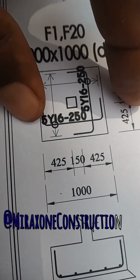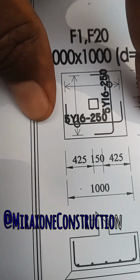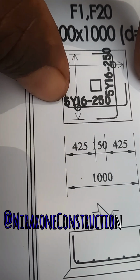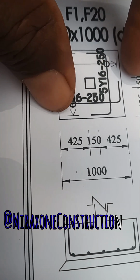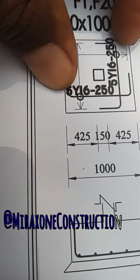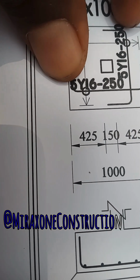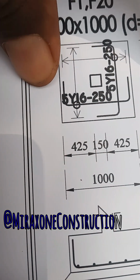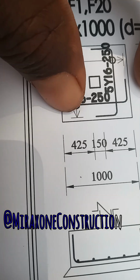It's not going to exceed 1 meter because the length is 1 meter. You have to give the gap of concrete cover. So Y here stands for high yield. High yield is a type of reinforcement. That is the one we use here.